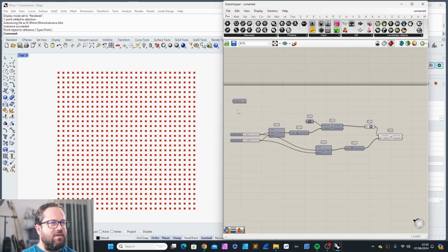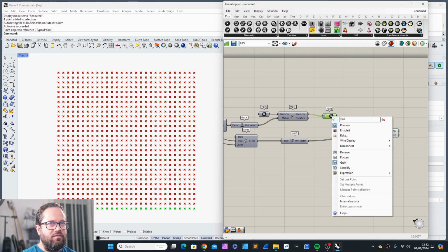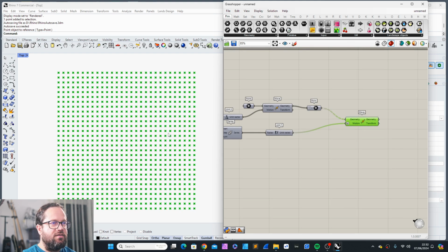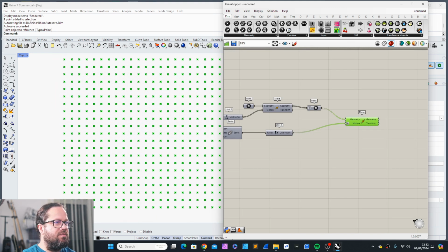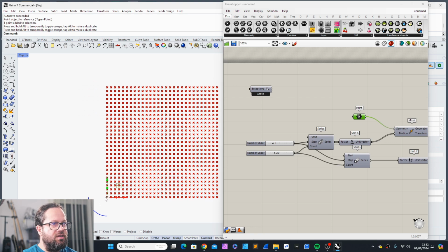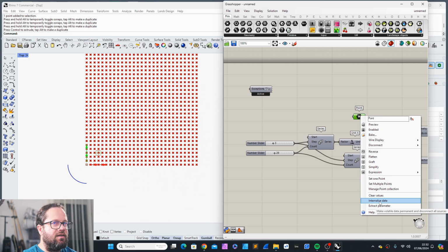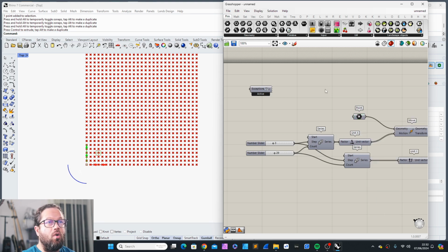The attractor is simple. Now I have this moved geometry. I've created a grid. I turn everything else off. This is my base. This is where I base everything off. What we can also do, currently this point is locked to this point in Grasshopper, in Rhino. We can also internalize the data, then it makes it fixed and it's inside Grasshopper. We can internalize geometry inside Grasshopper. Or we can create this point from scratch without any Rhino interaction.